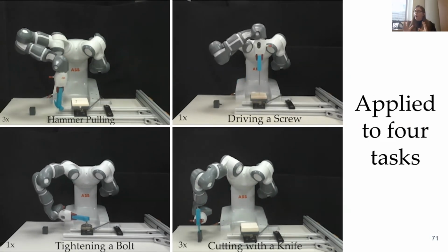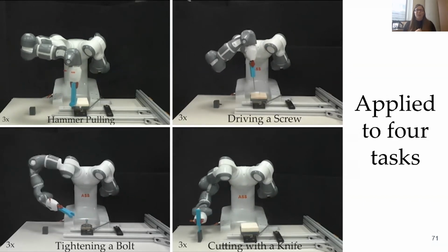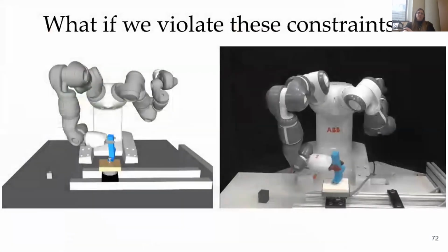Something, and pardon the pun, that I want to hammer home is that these constraints actually do matter, and you do have to reason over them. To illustrate that, imagine you listened to all this and said, I don't want to care about these constraints. Specifically, let's say you were to turn off the torque check, verifying whether it's a forceful kinematic chain, and plan with that check commented out.